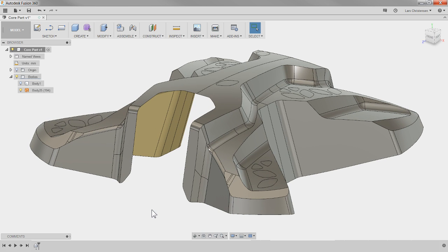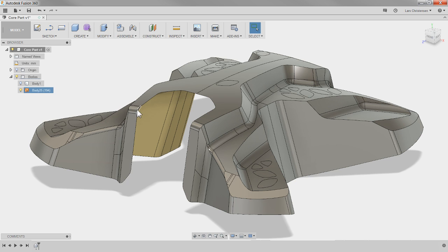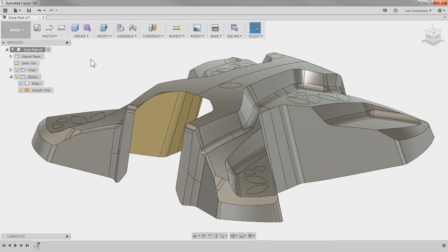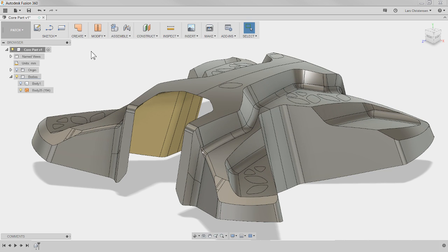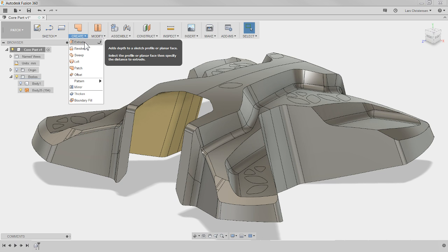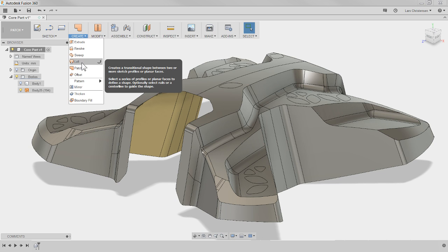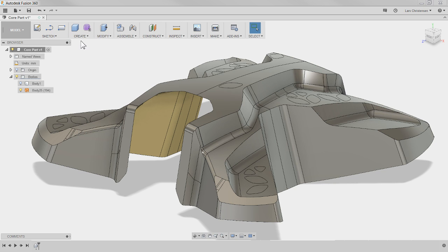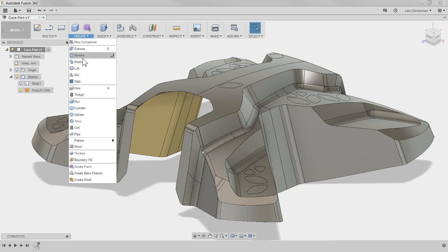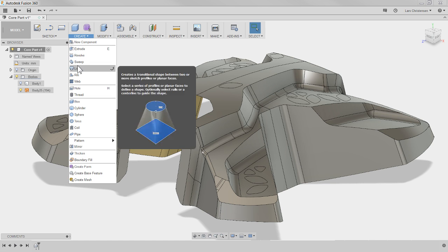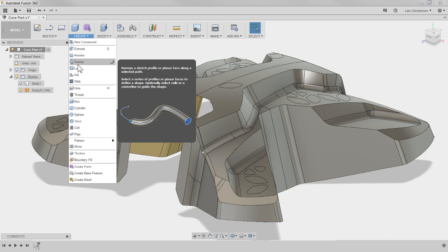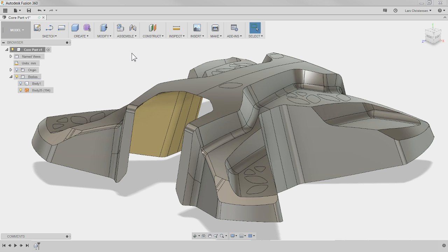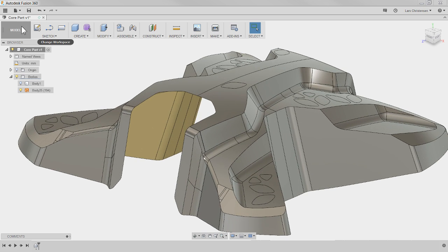The next thing I want to do is create some sketch geometry that I can use for creating a loft. And one thing I wanted to make sure you're aware of is that these commands, extrude, revolve, sweep, and loft, you've seen these before, right? Because these types of commands are the same ones we have over in the model environment, and they work pretty much the same way. The only difference is that these will actually, behind the scenes, stitch together and create a solid. I talked about this in one earlier live stream. I can't remember what number it is.